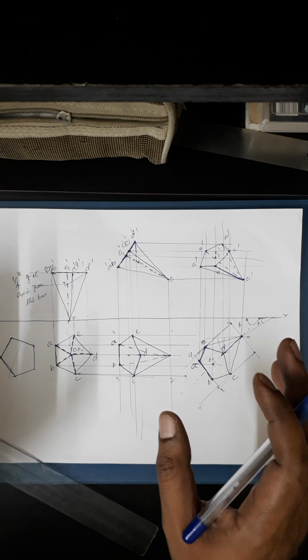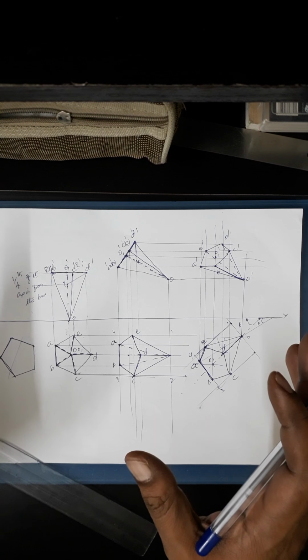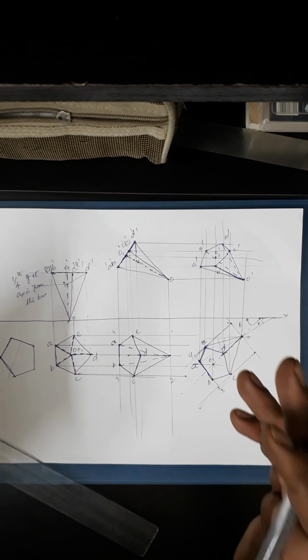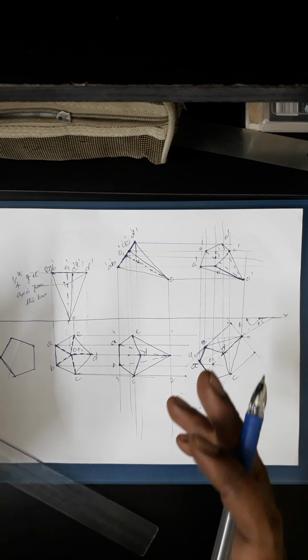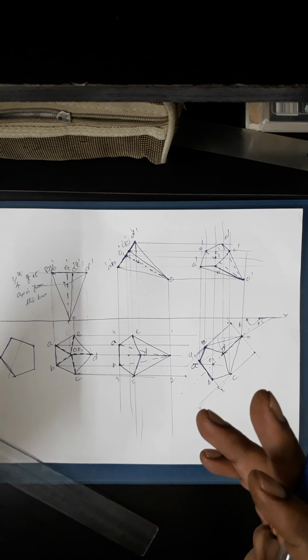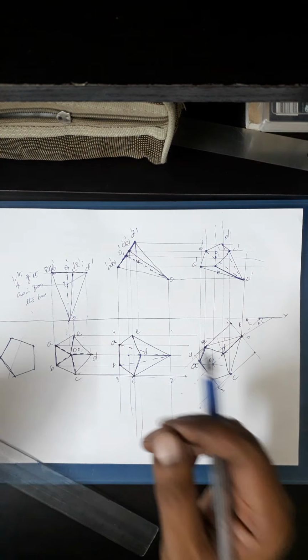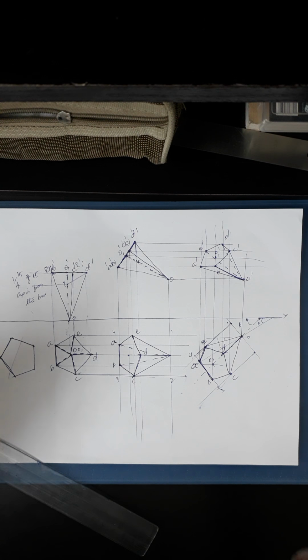So always when you have any pyramid, triangular, square, rectangular, pentagonal, hexagonal, any pyramid, go for the corner position. Let it be corner on the right side. So if they say in all the pyramids, they'll say that the pyramid dimension will be given, and they say which pyramid it is, and they say is freely suspended about a corner of its base such that the axis is inclined at 30 degrees to VP.